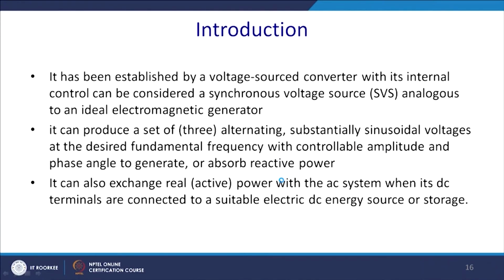It has been established that a voltage source converter with internal control can be considered as a synchronous voltage source, analogous to an ideal electromagnetic generator without any rotating part, and thus it does not have any inertia.